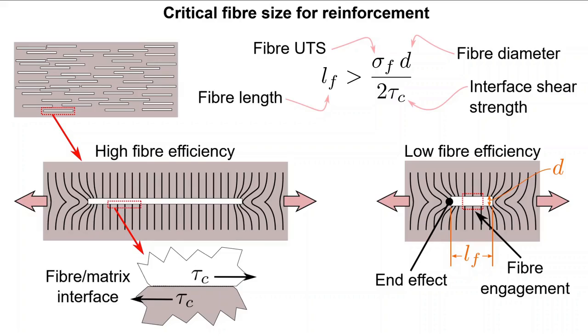This critical fiber size explains why a randomly oriented, short fiber reinforced composite will have properties being more uniformly distributed in any orientation. This means that it will be categorically more isotropic than a composite having a longer, more continuously reinforced matrix, albeit only in certain directions. This is because the overall interface relative to a loading direction can be significantly reduced, depending on the orientation of the fiber. If one were to change the aspect ratio between diameter and length to be approximately equal, then one would approach the properties afforded by a particulate reinforced composite.